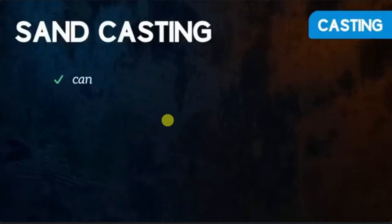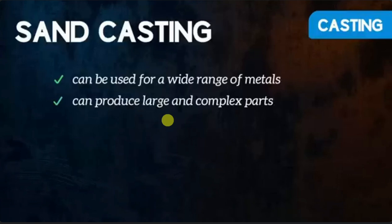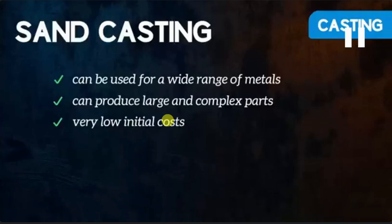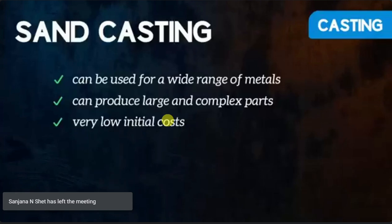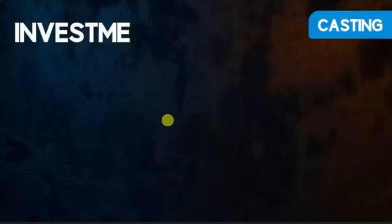Sand casting can be used for a wide range of metals, including those with high melting temperatures. It can produce large and complex parts, and initial costs are very low, making it good for small production runs. These are some advantages. Basically, this casting is meant for metals with high melting temperature, basically ferrous, and any complex shape can easily be produced. This is one of the oldest techniques, used in early days, and nowadays also we follow it. The initial cost is very low.